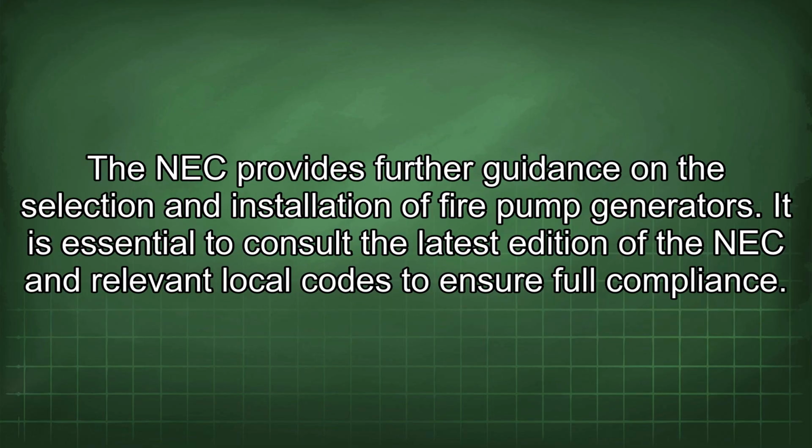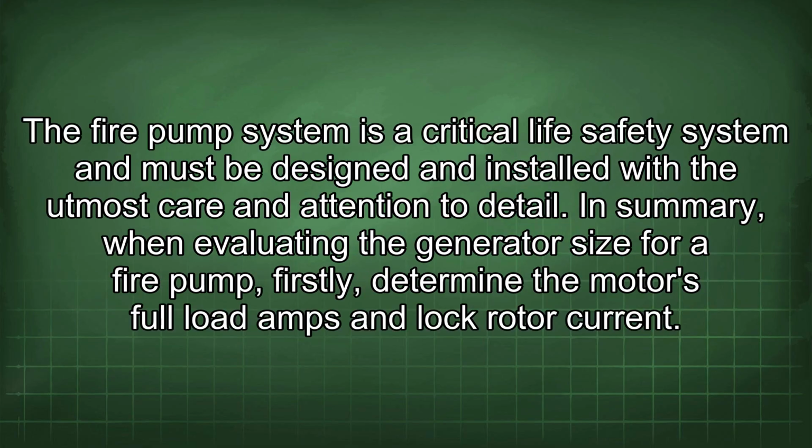The NEC provides further guidance on the selection and installation of fire pump generators. It is essential to consult the latest edition of the NEC and relevant local codes to ensure full compliance. The fire pump system is a critical life safety system and must be designed and installed with the utmost care and attention to detail. In summary, when evaluating the generator size for a fire pump, firstly, determine the motor's full load amps and lock rotor current.